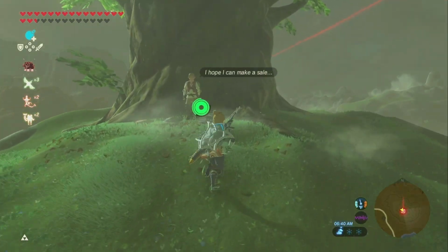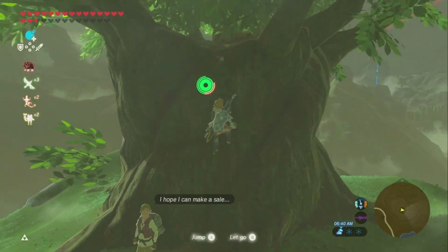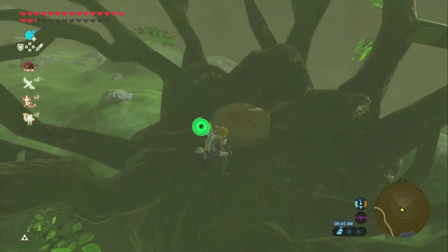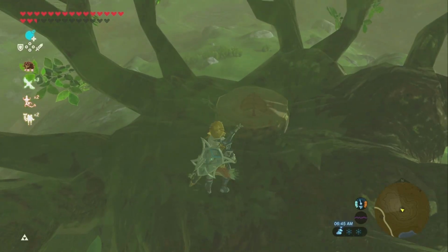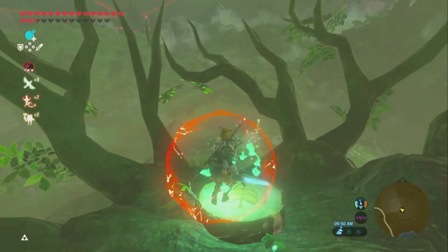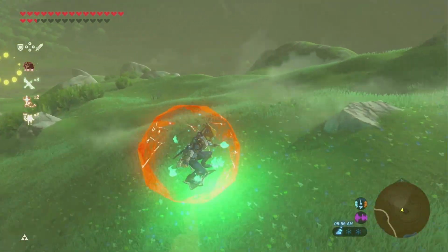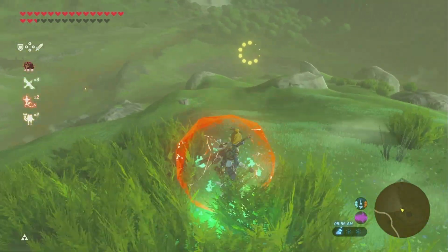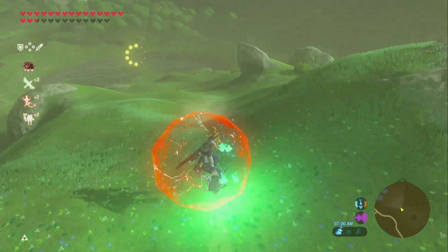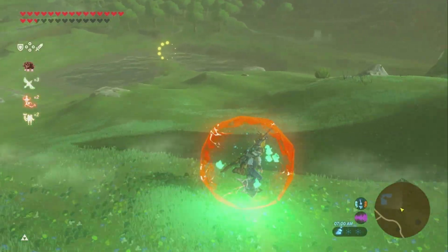Causes. There is no obvious reason for low pressure on the hot water side. You might look to the water heater. Occasionally, sludge will build up in the bottom of the tank and will obstruct the dip tube. This will restrict the flow of water through the water heater and result in poor pressure.